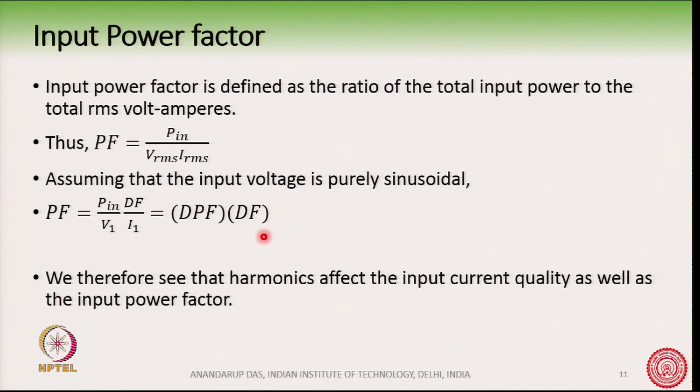And this relationship is noted because the effect of harmonics is not only to distort the current, but it also deteriorates the power factor. So, harmonics affect the input current quality as well as the input power factor. So, therefore, we need some methods to address this issue.